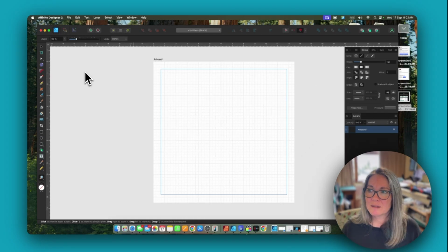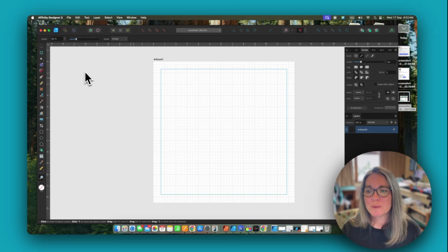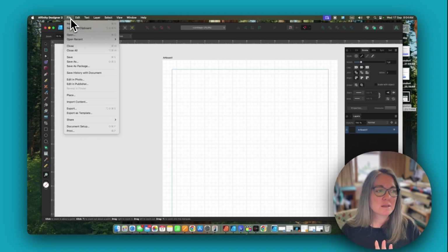You've got your workspace, you've got your most important tools on the right hand side. We're not touching the left hand side, everything that is there is fine. We have popped our snapping on, so when we do actually make something, it's going to be great. And we have got our grid sorted to inches and 1/4 of an inch. Okay, so now we've got our tools, everything set up.